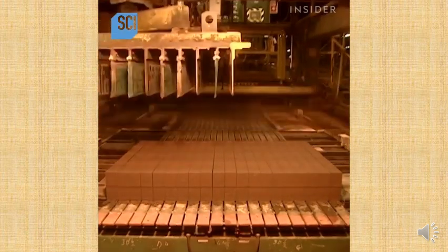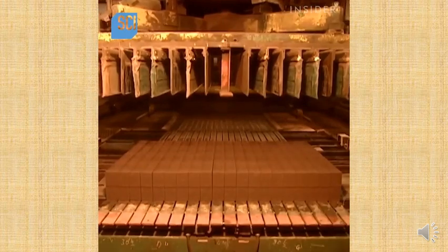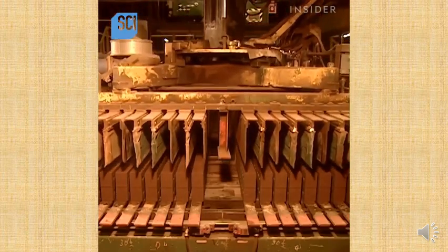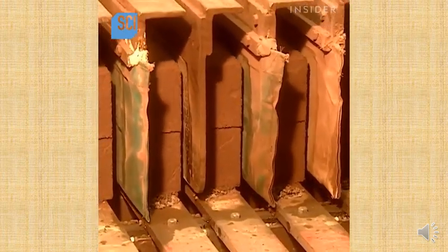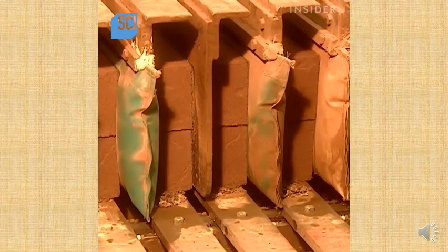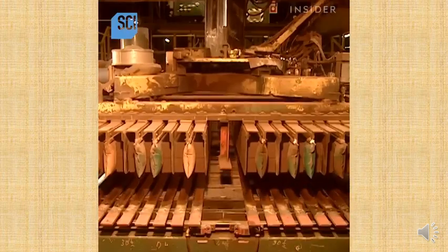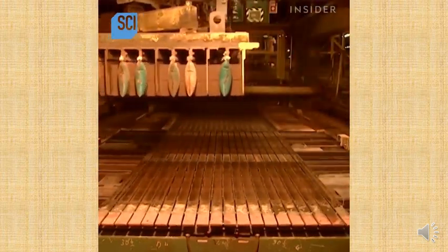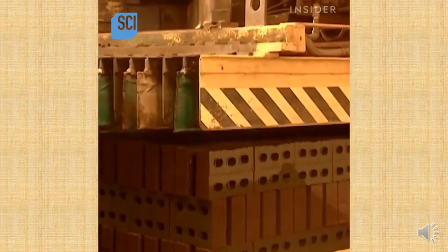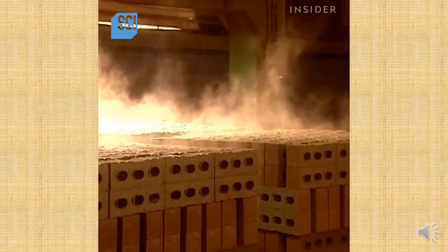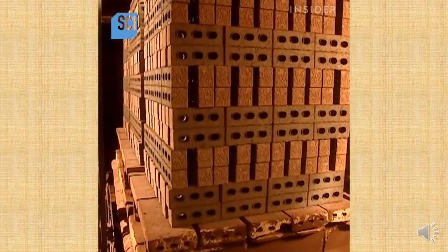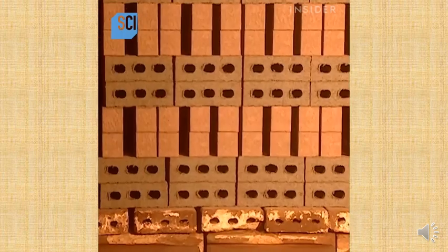Next comes the delicate job of stacking these newly minted bricks to be. A machine first separates them. Then, using inflating bags, it grasps them, raises them, then stacks them. Meanwhile, the water in the bricks is starting to evaporate. To hasten that process, the bricks go into a dryer for 2 days. The dryer gets its hot air from the heat generated by the kiln, where the bricks go next for firing.